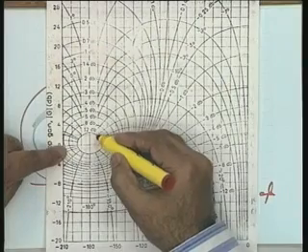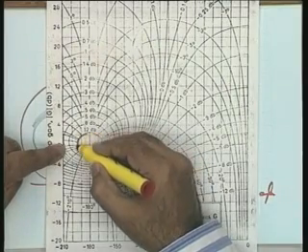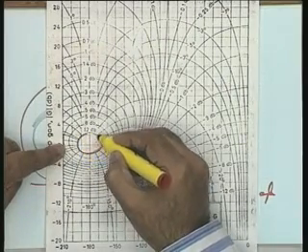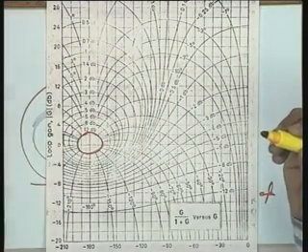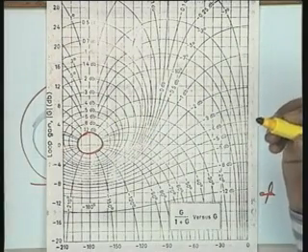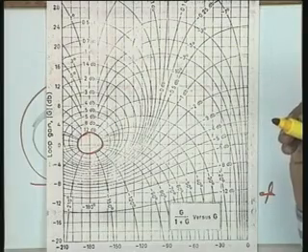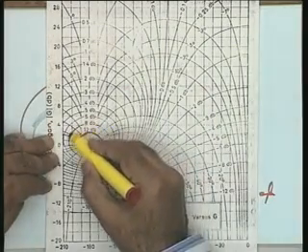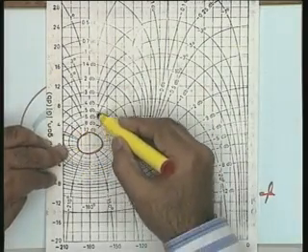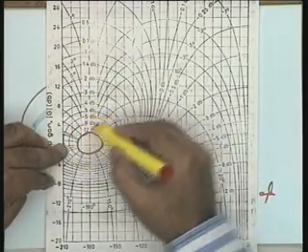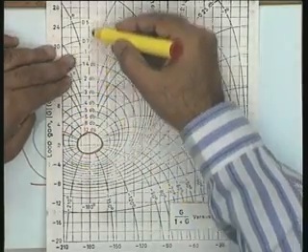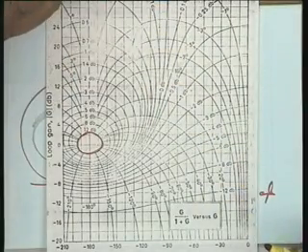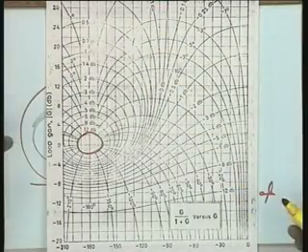You will see that this, I think I can put a mark over here, is the contour corresponding to M equal to 20 decibels, with the corresponding non-decibel absolute value, which you can calculate if you are interested. The next is M equal to 8 dB, then 6 dB, 5 dB, 4 dB, 3 dB and so on, and you go this way up to 0.25 decibels.